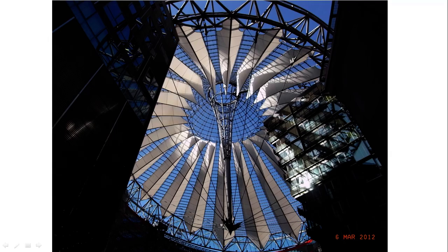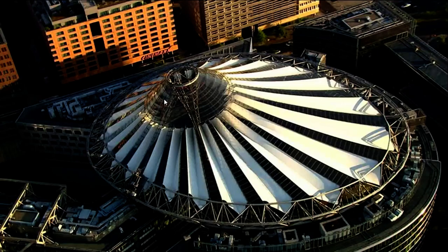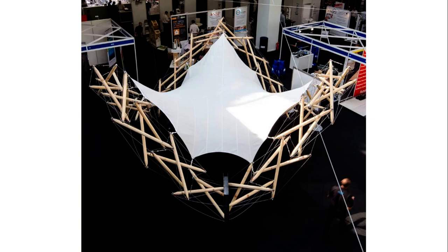So the load from most of that roof structure is coming back down into the mast, which is not hitting the ground, but is being held in tension back to the exterior truss around the edge there. Very elegant. It's a combination of that principle used in the Houston Velodrome with the tensegrity structure in the center.